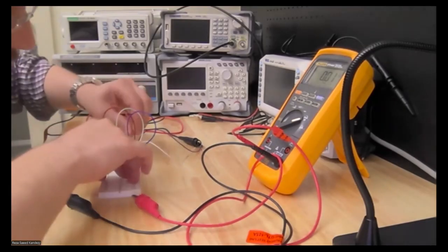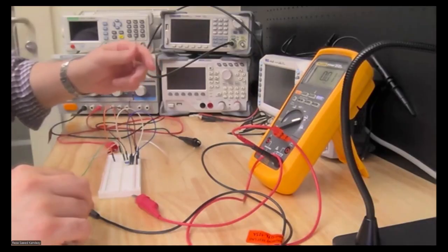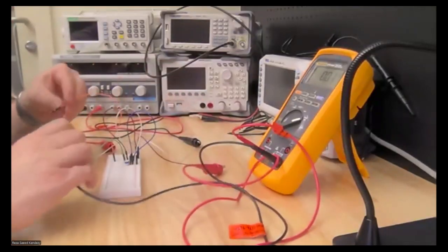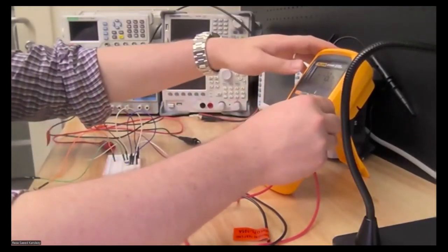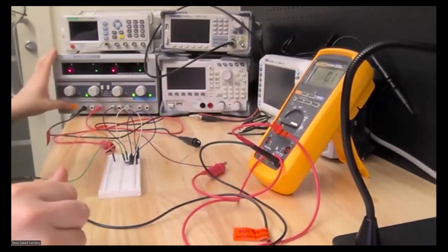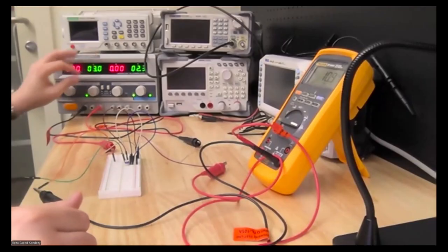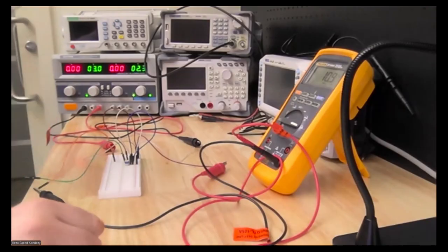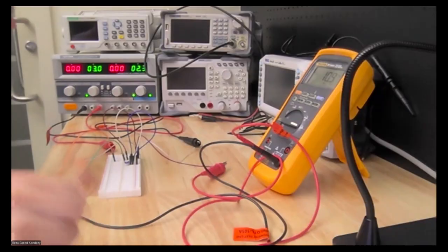So we need to set the current of the base, microamp DC. We are gonna go down. We want to check some of the voltages, so we want to have multiple measurement points. So right now I'm putting in 3 volts, and what I see is 10.9 microamps of base current. Okay, now we're good.